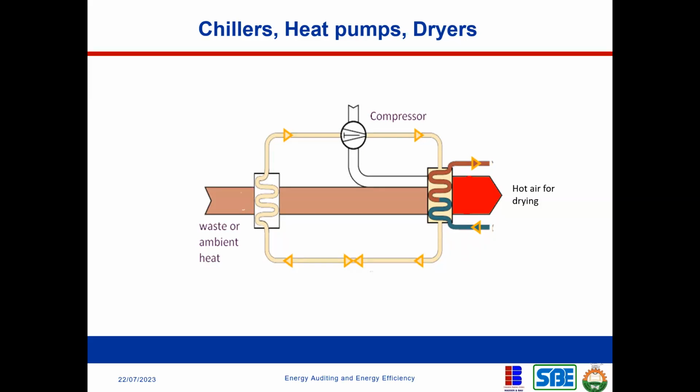So a heat pump is like, you have your air conditioning, just your normal air conditioning system that you have in your house. You have it, but now this is the hot area. This is your compressor, right? Now this is your condenser, which is hot, right? So what you do is that you can pass air around your condenser and collect the heat that is in your compressor and use that heat to heat your water, to produce hot water or drying air.